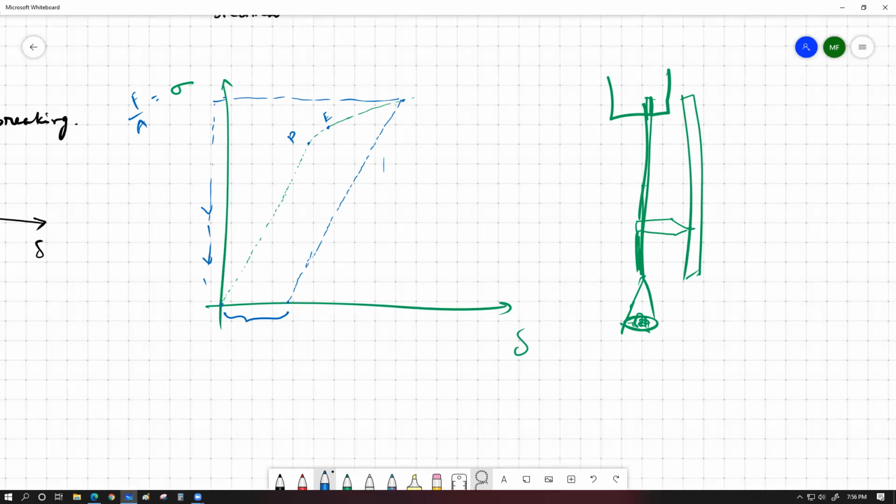So sir, it's basically fully dependent on our choice, as long as the material is within its plastic region. Precisely. If we load the object all the way up to the E point, which is the elastic point, and start removing load from anywhere before that, for example, if we load the object up to this much stress value and then start removing the load, the returning graph is going to be exactly the same. If we do it from here, same thing.